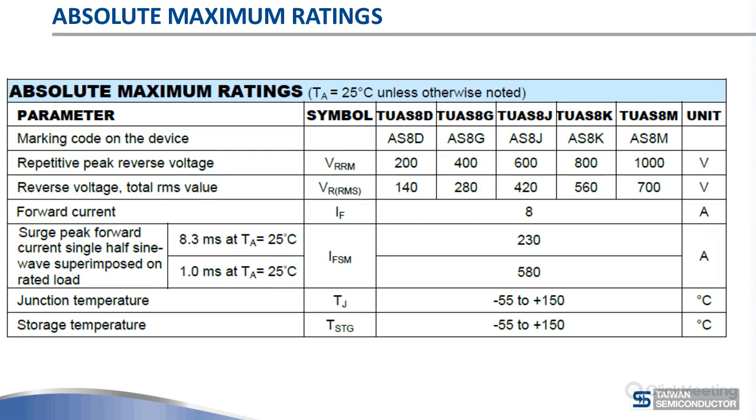You'll have thousands of rectifier data sheets that give you forward current as an absolute maximum rating, but it really isn't. The junction temperature is. Then the surge current is really an absolute maximum rating. If you exceed that, you will have a failure, and you will actually see failures once you start exceeding that by 10 or 20%. And then, of course, the junction temperature.